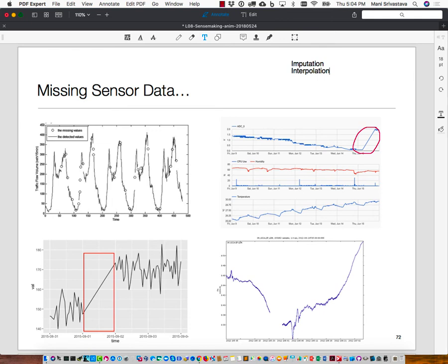So for example, maybe there are cross correlations between other sensing channels and this particular channel. So if I'm missing on this, I can refer to those. So between a combination of these, you can exercise some repair of the data. There are lots of situations that you face, particularly with wearables, right? They get loose. So maybe the physiological signal is not being picked up because the watch is not sitting next to the skin properly. So you might want to warn the system that the sensor is loose.